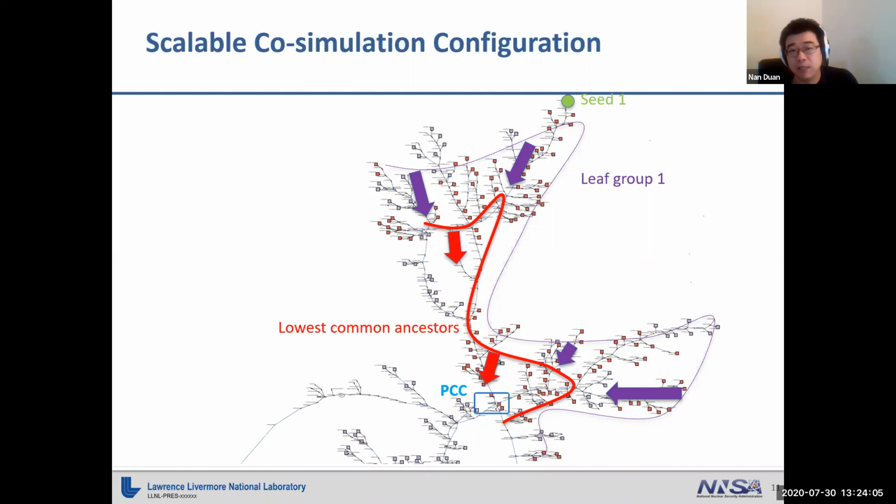So once that grid's net load is communicated between inverters, and consensus is reached that they are okay to reconnect, they will reconnect through the PCC and re-establish a new collaborative autonomy group.